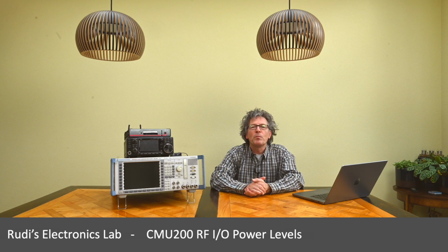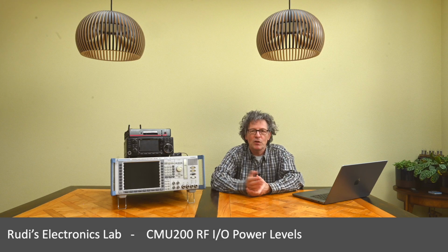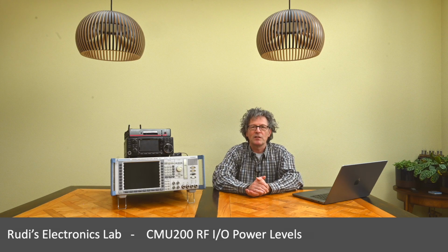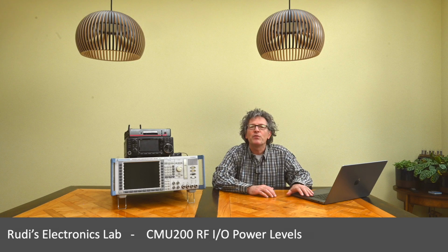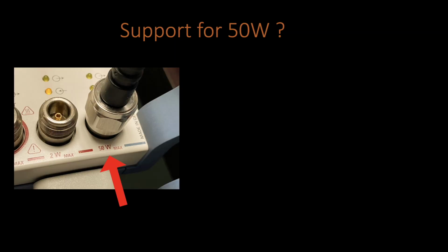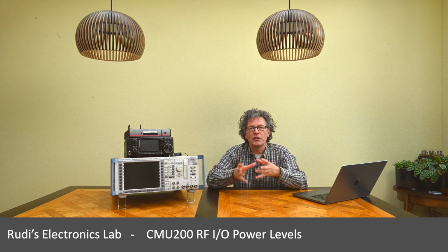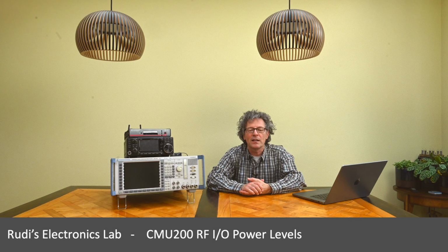But now to the more fundamental point in terms of maximum power that the device can handle, because all the inputs are 50 ohms as you would expect, so there's a maximum voltage that will result in a maximum power to be dissipated in the device. In some devices, if you're lucky, you will see 50 watts written on the front. That device will be capable of dealing with 50 watts of input power. And in my very first video of the CMU, where I also took one apart, we showed the huge cooling block and fan inside for it to deal with that.